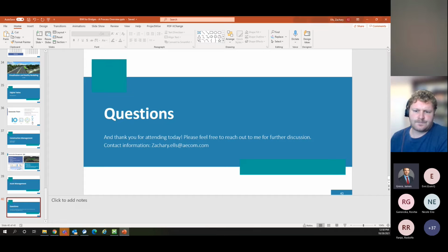Okay. All right, question in the chat is, can OBM do excavation and backfill quantities? Yes, it can. I don't know if I have one open now to show that, but that goes in. You have to make sure you have your surface and terrain model active. Based on where you've placed your footings, you can set limits for excavation on slope, on offset. You can account for sheeting by the way you cut through the excavation. And that's a report option as well.